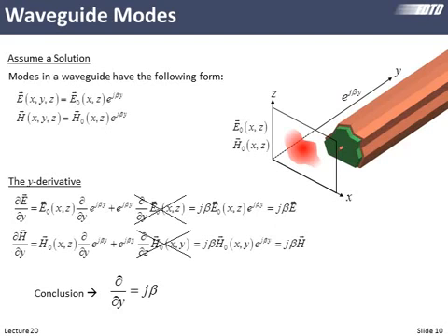So in a way, propagation of waveguide is very boring. The only thing a little bit more interesting that can happen is we might have multiple modes. There's different amplitudes on each of those modes, but they propagate independently. They don't scramble energy unless there's something about the waveguide like a bend or a bump or something like that. Now they travel at different velocities because each mode has a separate propagation constant, and they may go in and out of phase, but their amplitude cross sections for each individual mode is just uniform, and nothing changes in the direction of propagation. So the mathematical form of our modes is shown at the upper left. The overall electric and magnetic fields as a function of x, y, and z has these amplitude terms, which is just in the cross section, in this case x and z, and then the propagation terms in the y direction.